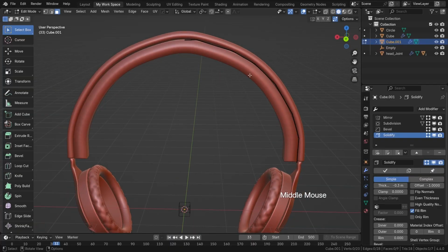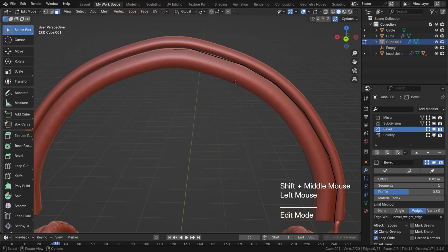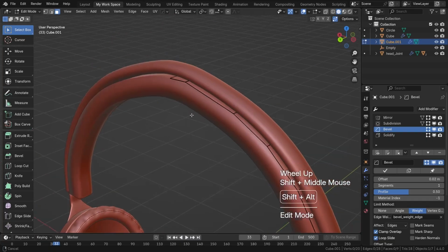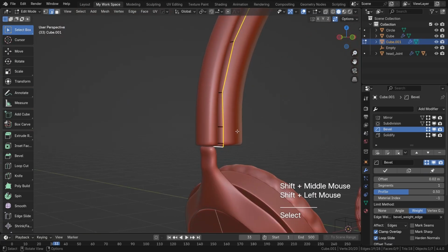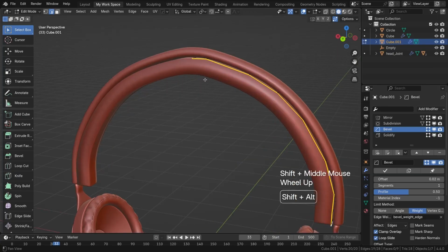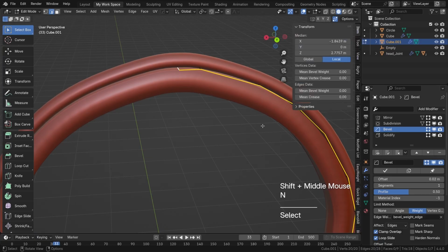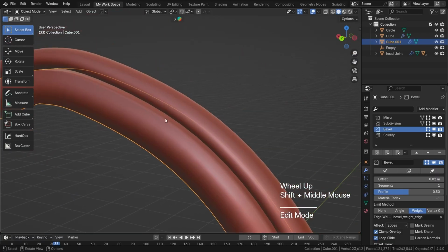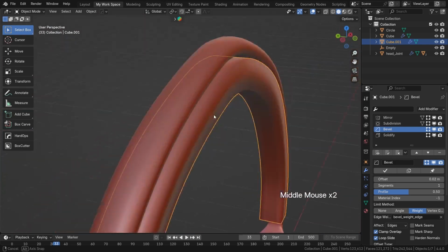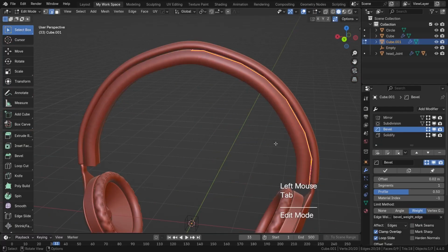So that method, I will use the bevel method to weight here, and here I will select these edges, these ones, this one, yeah, and this one, and here I am going to add some crease, so that it will not be affected by our subdivision surface modifier. You can see it's flattened now.